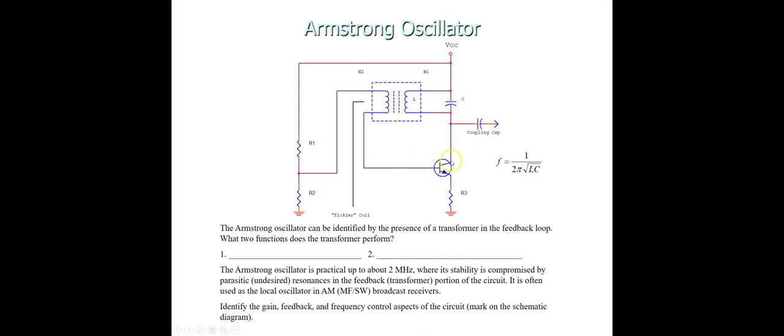and then the collector side of this amplifier will be connected to VCC, and the current will flow in this way. This will be shorted and the current will pass through from here to here. So here this transformer is basically short circuited in case of DC, and this will be open circuited.